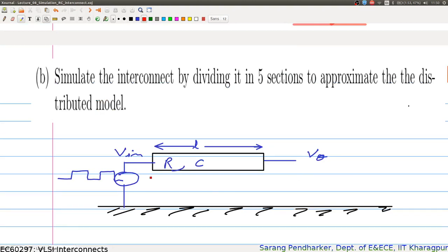Again, you may have to further reduce the clock frequency to look at the waveforms properly. So your on time should be enough that all capacitors are being charged. You may have to adjust that.